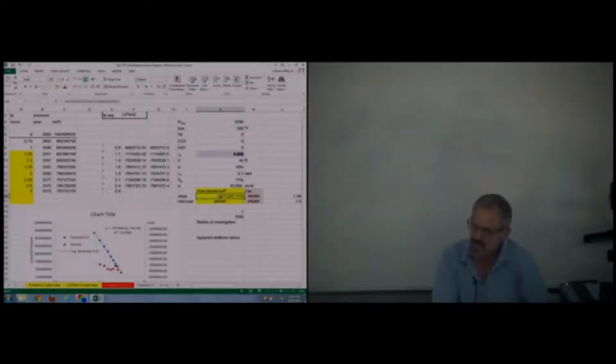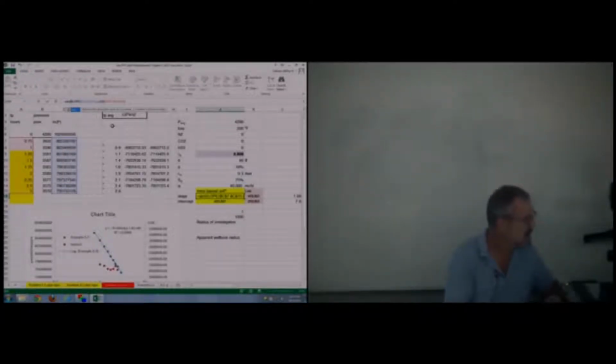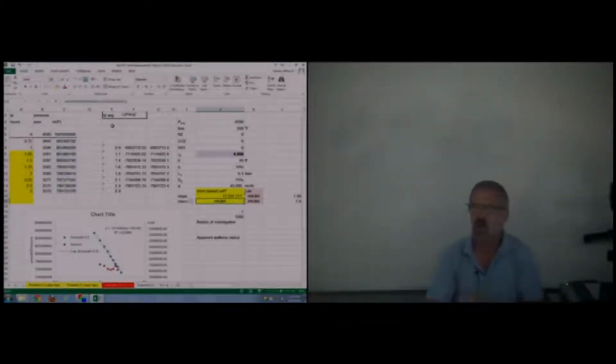And all of the equations that we have in the tables of the textbooks, you'd think that they flip the signs for drawdowns and buildups, because obviously the pressure goes in one direction on a buildup and goes the other direction on a drawdown. But it's always the absolute value. So if I want to make this a template so it works for buildups and drawdowns, I would just say ABS. Because all of my equations are expecting a positive slope.